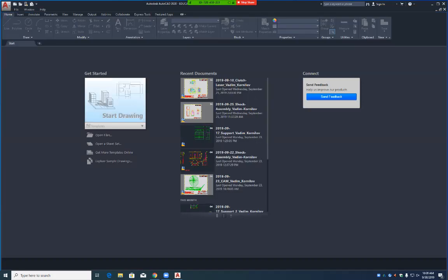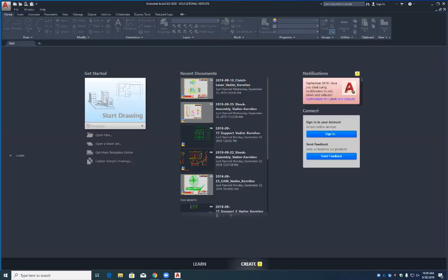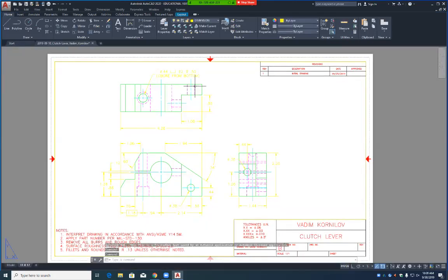Now, if I had a shaft right here, with the center line right through here, and if I had to put a keyway in here, the center point of my keyway would be the center point there. It'd be on the quadrant point of my shaft. Does that make sense? On that quadrant point.